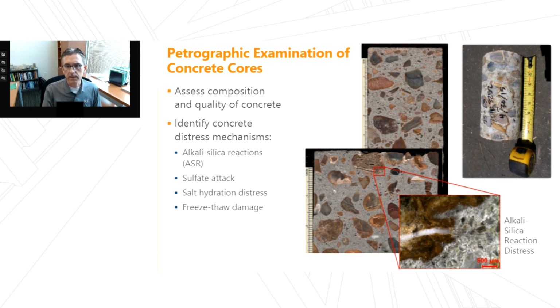But what we're primarily interested in is understanding whether there are any concrete-specific deterioration mechanisms. So those could include alkali-silica reactions or sulfate attack from sulfates in the seawater, or if we're in cold environments, looking at the extent and severity of freezing and thawing damage to the concrete.